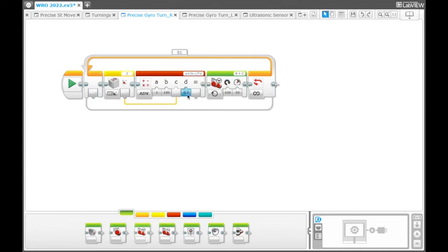If you are giving some value, let's say 0.6, 0.7, whatever, and at angle 175 or 176, maybe 179, your robot power is so low that it cannot push the robot to angle 180. So for that we have to give a little push at the end, and we can give that A parameter a value of 5 or 10, anything. You can give a very little power to just give a small push.